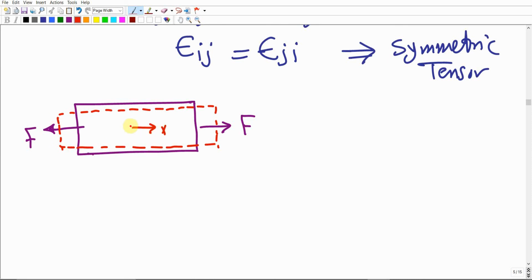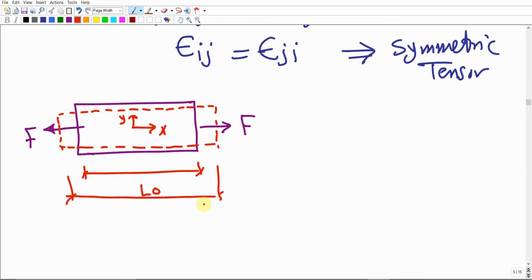So if you consider this is the x-axis and this is the y-axis, right? This was an initial length L0, now it will attain a new, bigger length L. So we don't have a change in what? A change in the dimension. We had a dimension L0, and this dimension became another dimension L, another size, right? The same thing for the lateral direction. If this is D0, the original diameter, it will attain a new diameter D. So there is a change in dimension, but in the y direction. Make sense? But do you think that this bar has experienced any change in the shape? It is still a bar. It is still the same shape, but with different dimensions.